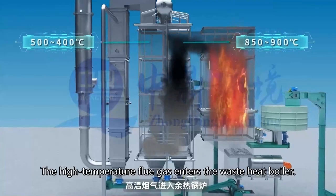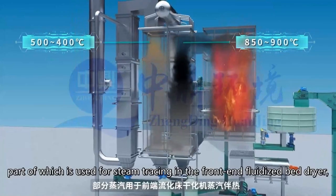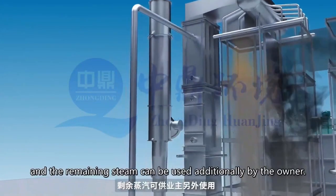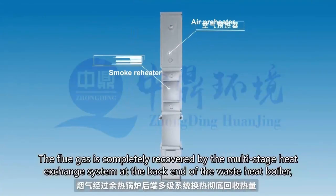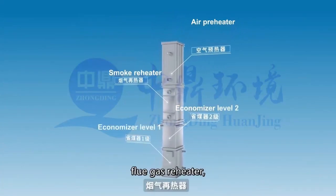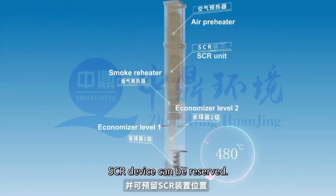The high-temperature flue gas enters the waste heat boiler to recover heat and generate steam. Some of the steam is used for steam-assisted drying in the front-end fluidized bed dryer, while the remaining steam can be used separately by the owner. The flue gas goes through the rear multi-stage heat exchange system of the waste heat boiler to completely recover heat, including the air preheater, flue gas reheater, evaporator, economizer, etc. A position for an SCR system can also be reserved.